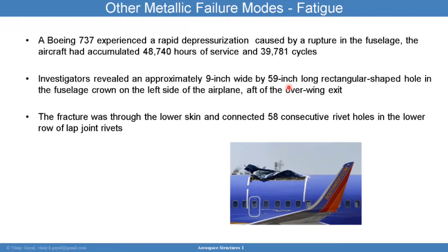Well, that pressure cycle puts stress on the fuselage due to the pressure difference across the fuselage. As you ascend in flight, the outside pressure is low, the inside pressure is highly pressurized to the level that's comfortable for the passengers, and the pressure differential causes a hoop stress and a longitudinal stress. These stresses then put loading conditions into the skin.